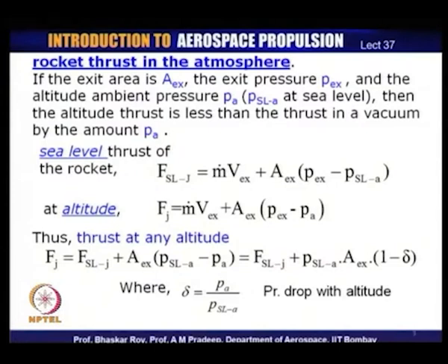If we write a generalized version of thrust at any altitude, we can write F_j is equal to F_SLj plus A_ex into (P_SLA minus P_A).